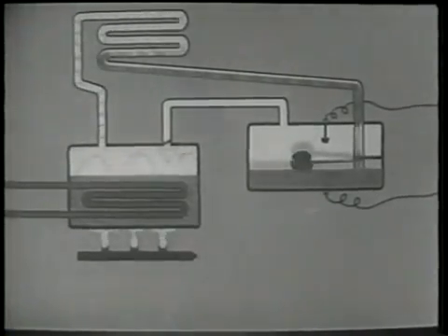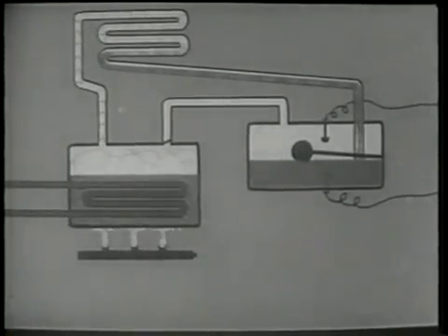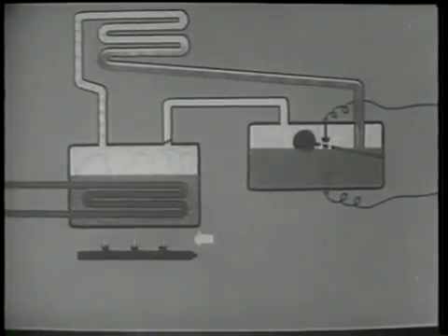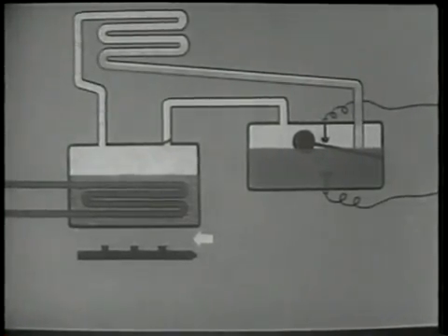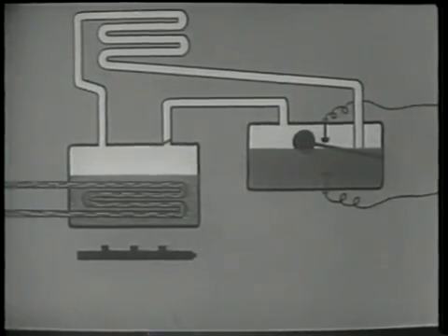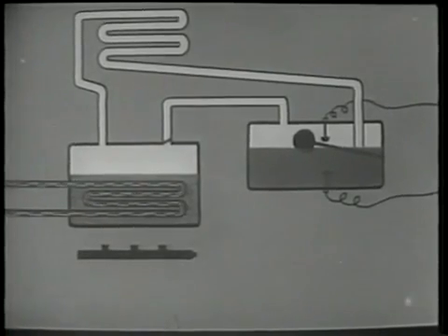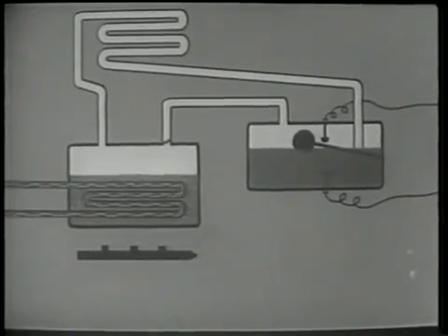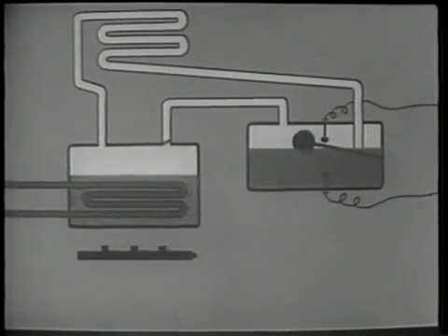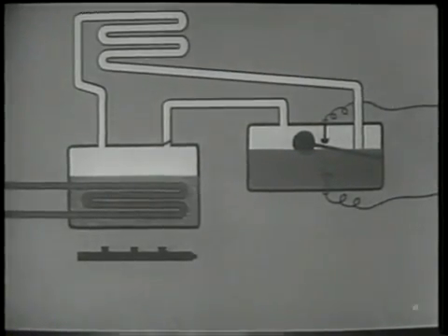As the liquid refrigerant accumulates, the float rises until it reaches an electrical contact point, setting off a device which automatically turns off the flame of the burner. The same device also sends a stream of water through the coil and the generator. The absorbent which surrounds the coil is thus cooled.